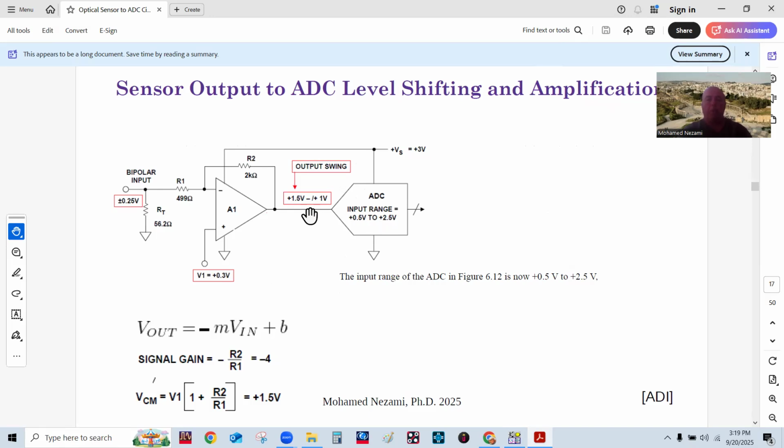So usually the DC offset in here is presented so that when you don't have any signal in here, your sensor output is parked in the middle of the range for the ADC. So let's put this at 1.5 volt in here, okay? And then in that case, on top of the 1.5, we need to have this signal range from the minimum to the maximum, which is this range in here, which is 2 volts. So meaning we have 2 volts full scale to play with. So we're going plus minus 1 volt in this case. So that's what we need to do here.